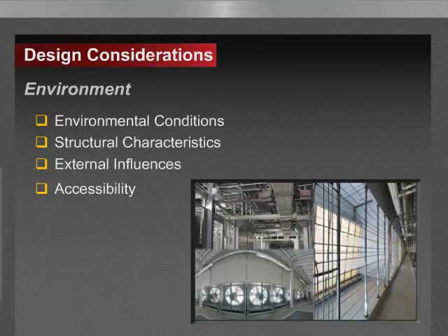External influences: could fresh air intake for cooling or makeup introduce contaminants which may affect network reliability or be the source of unwanted alarms? And of course, the consideration of accessibility once installed or for the installation. That is, for maintenance, test, and inspection within subfloor, ceiling void, above cable trays, or within fully or partially enclosed equipment cabinets, and so forth.